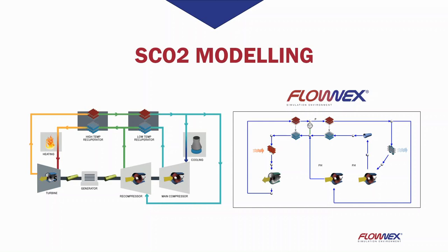Each major component is modeled accordingly as to ensure that the correct pressure drop and heat transfer phenomena occurs. Over here we have the turbine, where the turbine can be modeled using various correlations, such as the restrictor with loss coefficient or the ellipse law, or the component can contain a turbine performance chart. The compressor can also be modeled using a compressor chart over here.